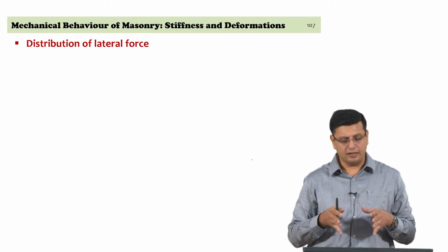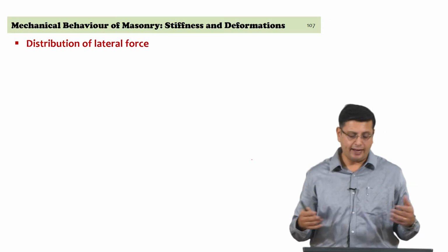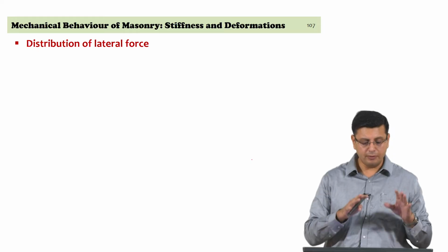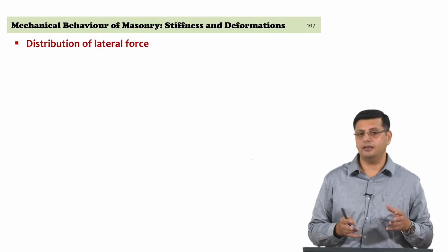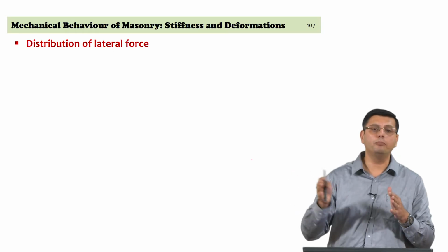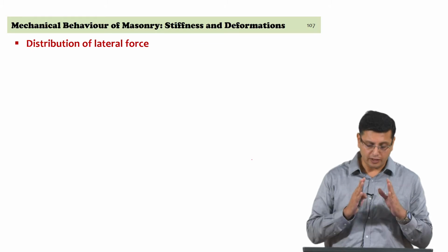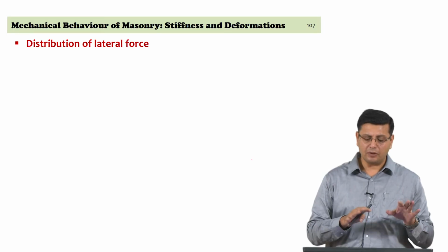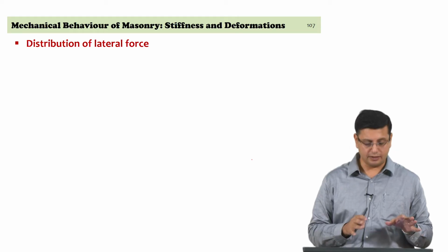The intricacies in terms of different methods that you will have at the scale of an entire wall, we will examine as we start doing design problems, but the overall framework for how lateral force distribution occurs in a masonry building all the way up to a masonry panel, a masonry component, is important to understand, because there are assumptions that you have to make on the behavior of each of these elements and the system as a whole. And my focus is primarily from the point of view of earthquake response of masonry structures.